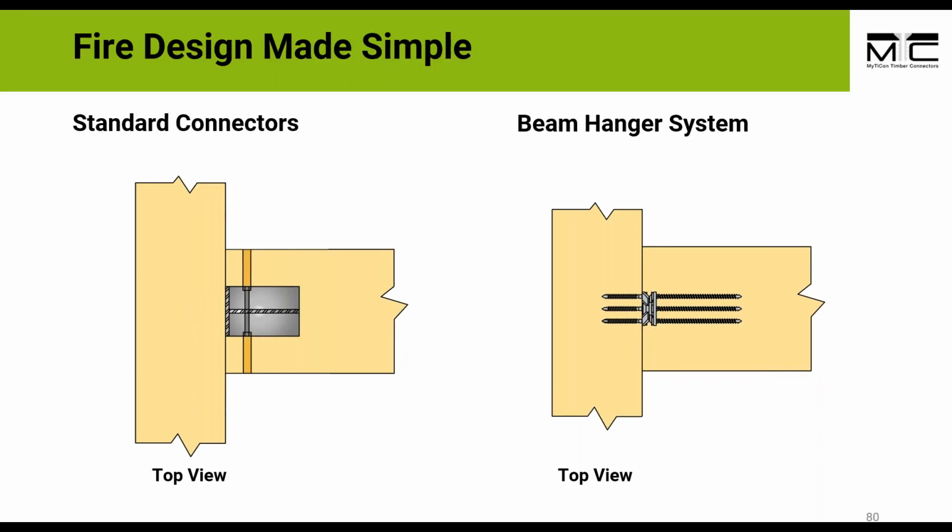So after providing that wood plug, you'll have to provide additional cover. You have to screw that additional cover. And for the char contraction, you would have to provide more wood pieces and also attach those wood pieces correctly. And from all of this, you can see that the fire design is really complex. And that's in addition to actually designing the connection itself.